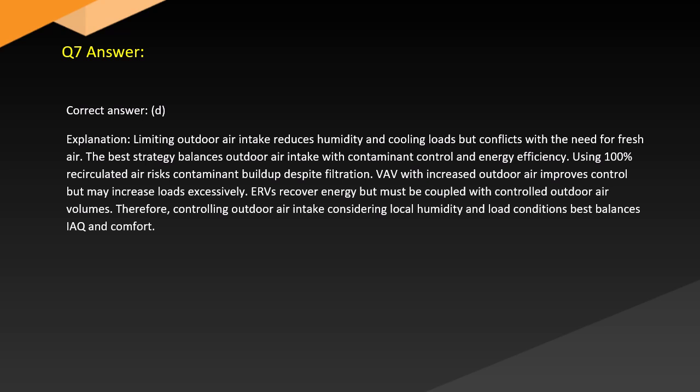Answer. Correct answer: D. Explanation: Limiting outdoor air intake reduces humidity and cooling loads but conflicts with the need for fresh air. The best strategy balances outdoor air intake with contaminant control and energy efficiency.